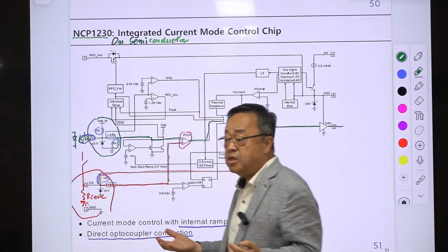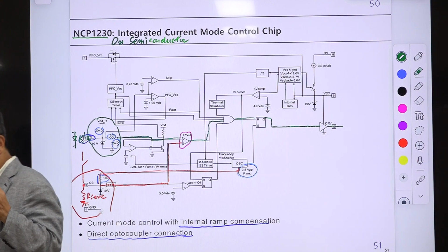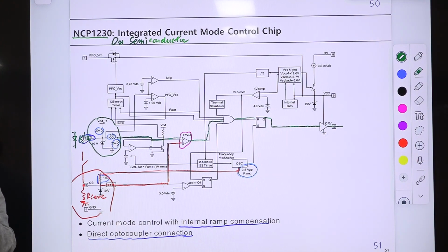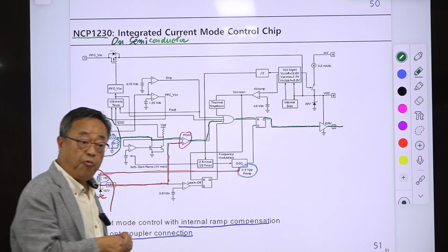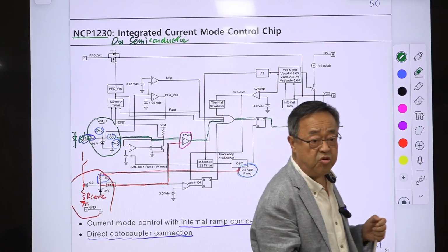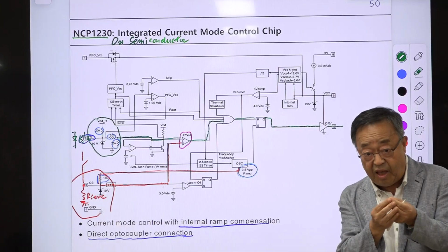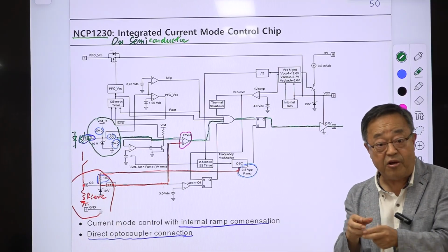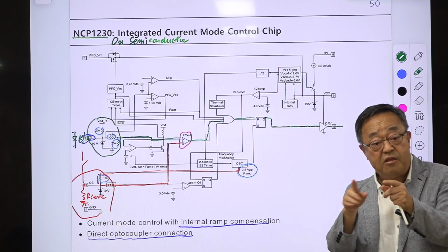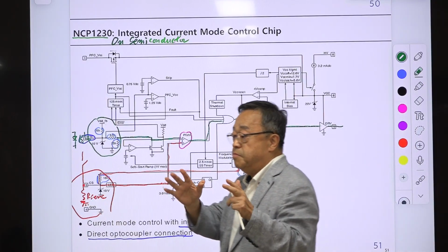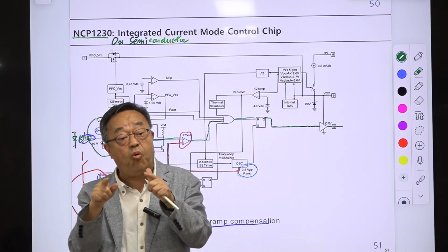So I proposed there should be a special process called a smart power process, which can build the chip and the switch all together with the same process. That process was not available. So the way our team selected was to take the MOSFET chip and the IC, put them together in one package, and put everything in a TO3 package.